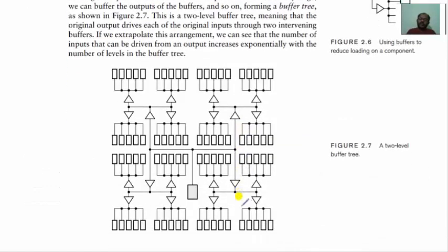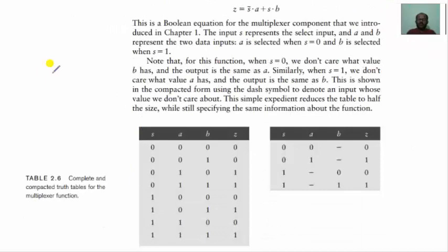You should know the clock division circuitry using a buffer tree. Now look at this: in the case of synchronous design, each and every clock pulse should reach each and every flip-flop at a specific time, that is, the clock should arrive only at the given time. If there is a delay in the clock arrival, it results in clock skew. So in order to overcome this clock skew, you are going to make use of buffers.